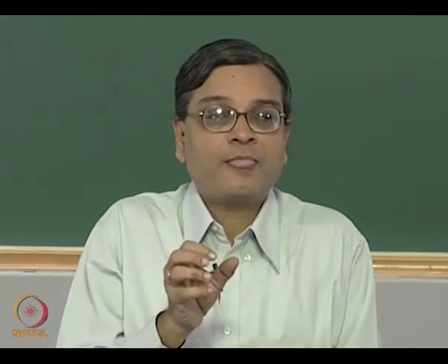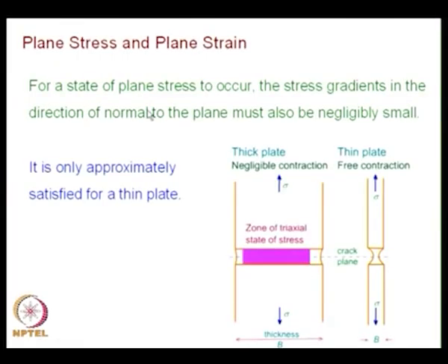So, you will have sort of a tension-compression type of situation in the plastic zone as well as the elastic zone. So, you will have gradients of stresses developed in the thickness direction. So, in the context of fracture mechanics, though we say thin plates subject to in-plane loading can be equated to a plane stress situation, from the definition of applied mechanics, the definition is strictly not correct. It is only approximately satisfied in a thin plate.